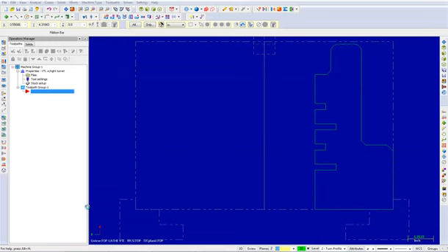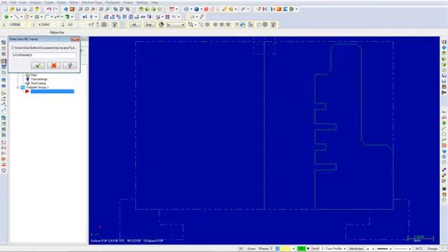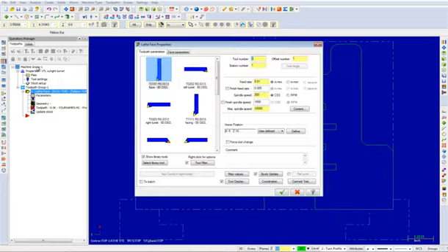The first toolpath that we will create on the part is a facing toolpath. Select the facing icon. When the new NC name dialog box appears, choose the OK button to accept the default NC name. Select the Face 80-degree tool and input the comment, "Face the part."